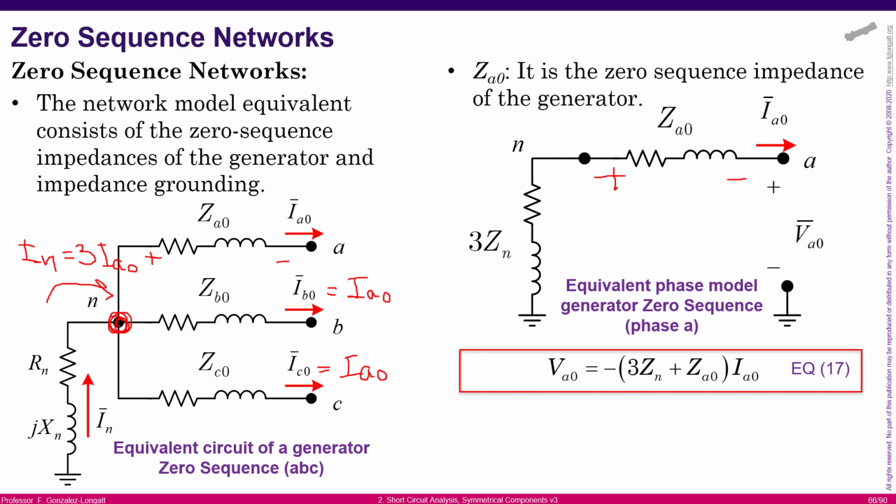Okay, we are clear. But the next point is probably the most interesting one, because the next one must represent the voltage drop across the neutral point, between the neutral point and ground, okay? And what you need to understand is that in the neutral point, because the zero components are moving here, 3 times the zero components is moving across this impedance. Now, what we need to understand is the following.